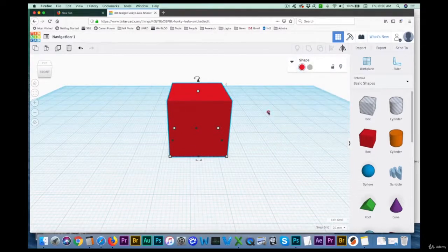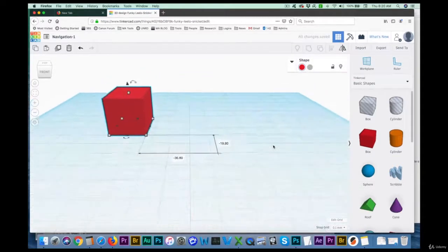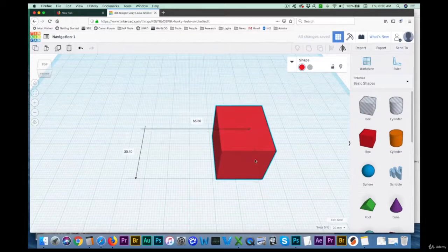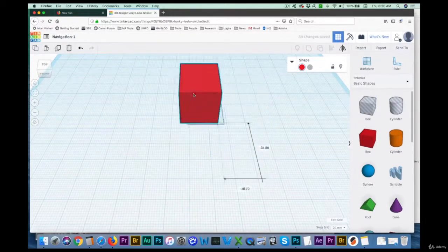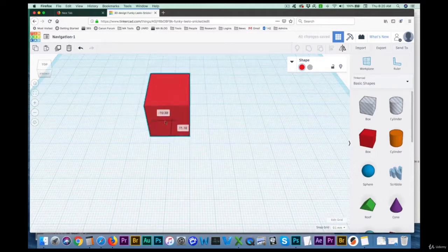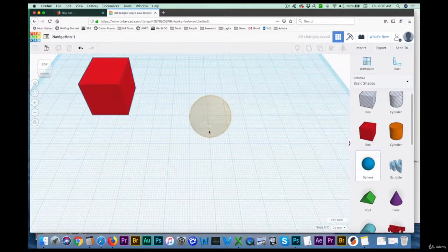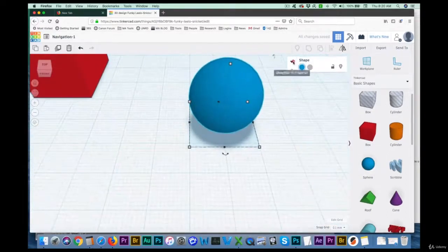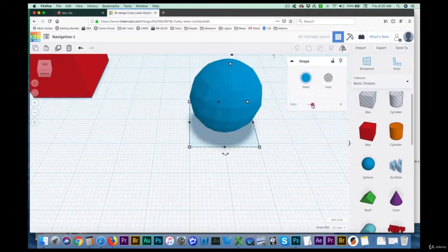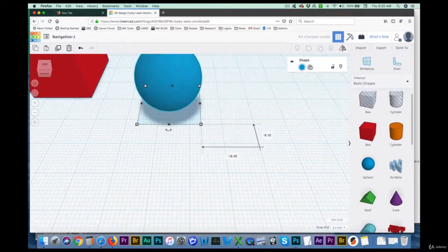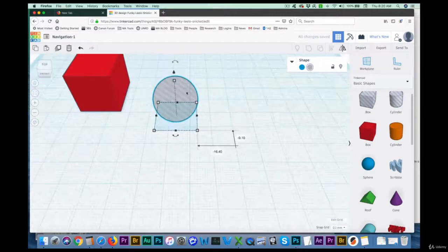What I would recommend as an exercise, and I would really strongly recommend you guys do this: you see that when I click and move this, it's telling you how far you move it in certain directions. So we have an idea. All these things are going to come into play. Start getting comfortable with the different shapes. Come in here, take a look at the different controls we have for each shape. Practice changing it into a hole.